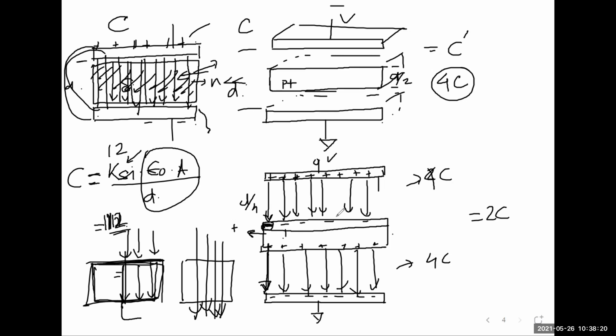So P plus, heavily doped P plus looks like a metal basically. Okay. So if it is like a metal, then obviously you're going to get free carriers on both sides. And obviously it's not free carriers on both sides. The big difference between the metal and this thing is that you actually get almost a free carrier on one side and negative on the other side. Here it's a mobile carrier because it's in a lattice, whereas in a metal, it's actually a lattice there too, but the mobility is much higher compared to P plus. Okay,